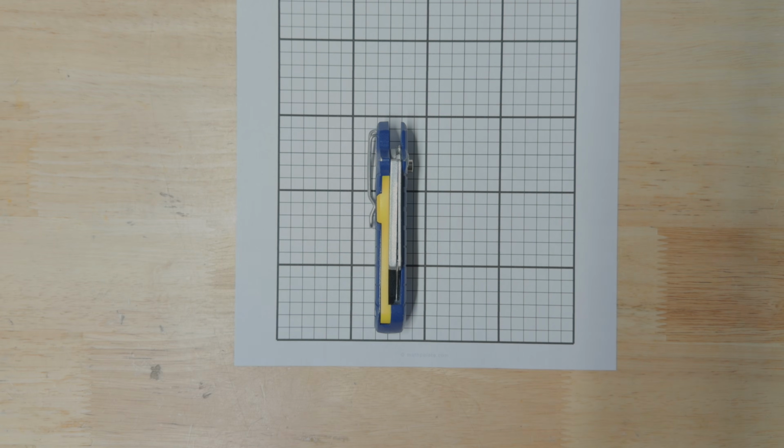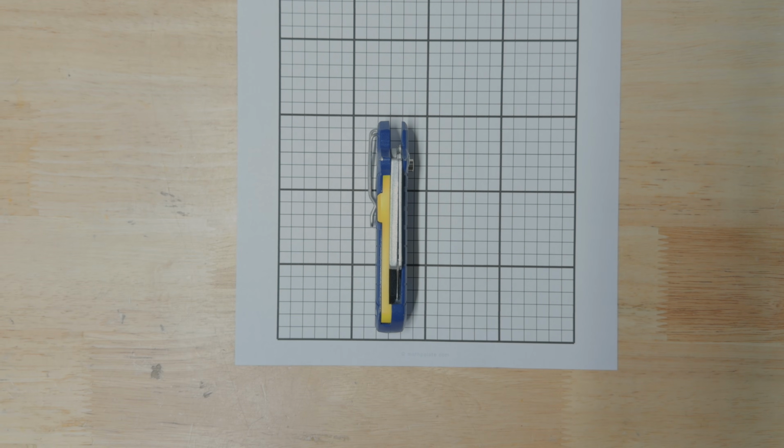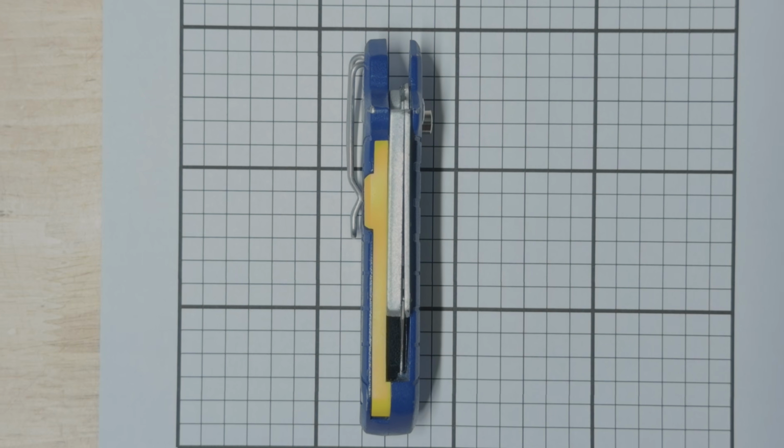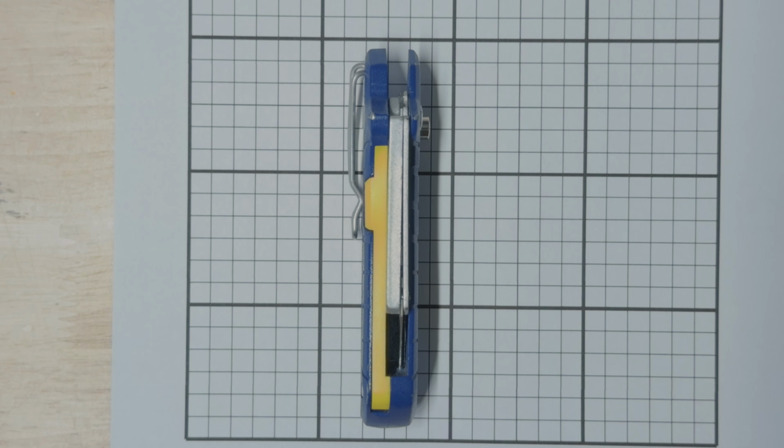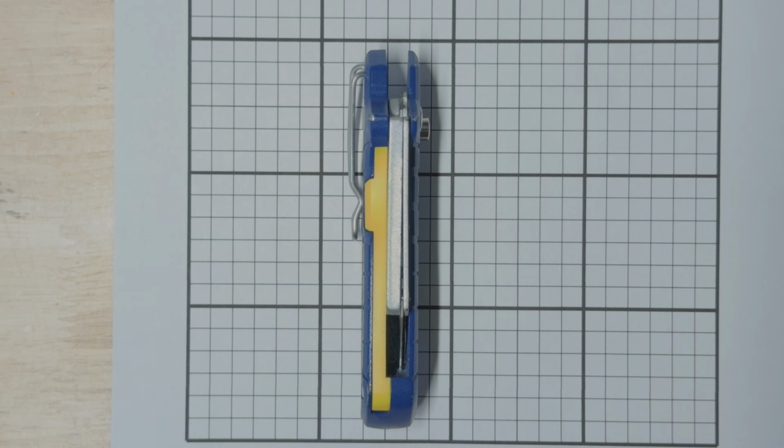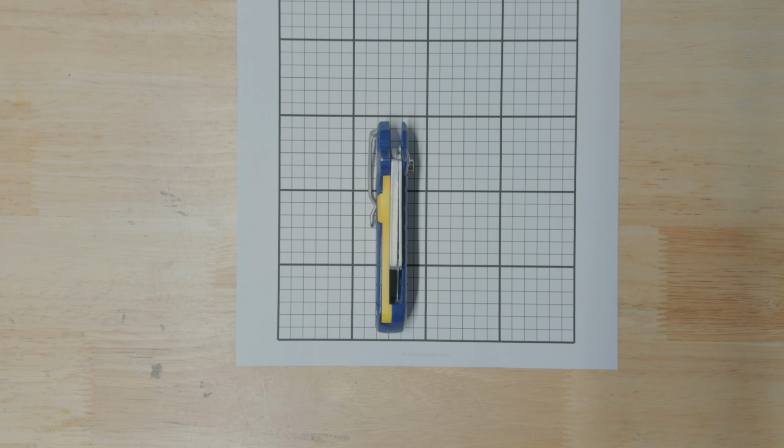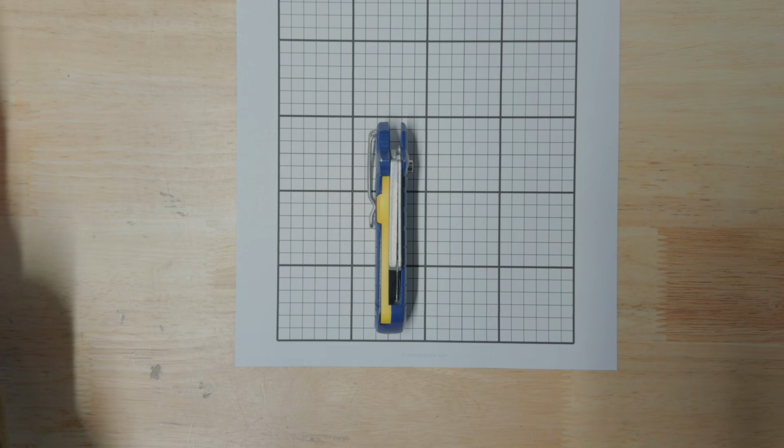So starting with this first example, I placed my X-Acto on the grid, and I found that taking a picture a little bit higher and zooming slightly while using the crosshairs to stabilize the picture made for tight accuracy of the part's outline and reduced some of the distortion from being too close to the part. From there, simply upload the picture to your computer and then we'll go jump into Fusion.